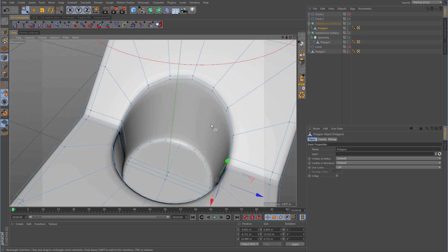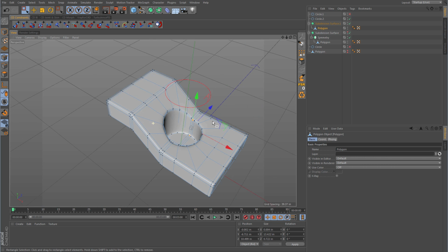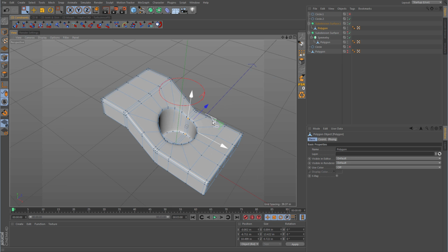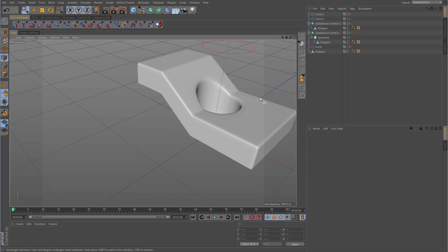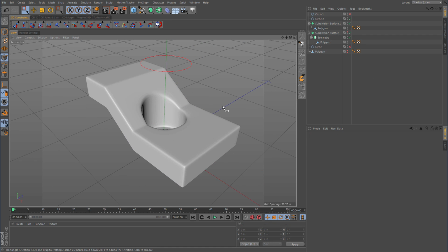where you have an angled object and you're trying to extrude a round cylindrical hole into that, where half of it is flat and the other half is up at an angle, but you want to maintain that nice defined edge there. Obviously, not having enough geometry is going to result in pinching. You can try weighting, adding more cuts, more control edges, but you saw it was causing the pinching and problems. So the only solution to this is just to add more geometry to it.